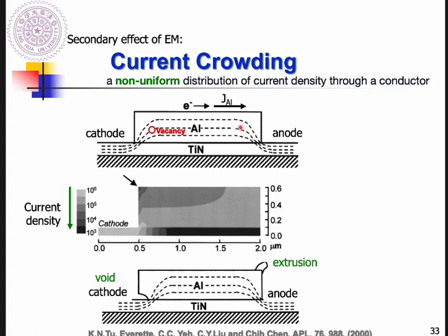In the beginning, you can visualize aluminum atoms accumulating at this bottom right region, which causes the stress gradient. This is the atomic flux. In the meantime, the primary vacancy flux goes in the opposite direction, to here.